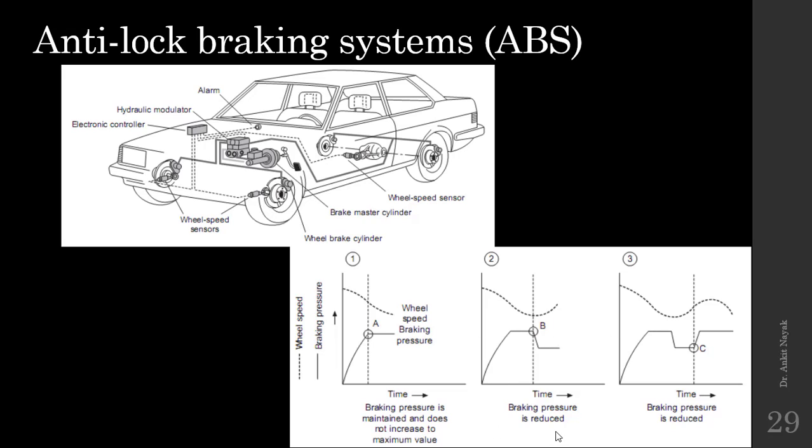And in here you can observe the second case, where the braking pressure is reduced after reaching a particular amount of deceleration, or I can say after reaching a particular speed, this braking pressure will reduce, so that the wheel will continue rotating, or will be in revolving motion.